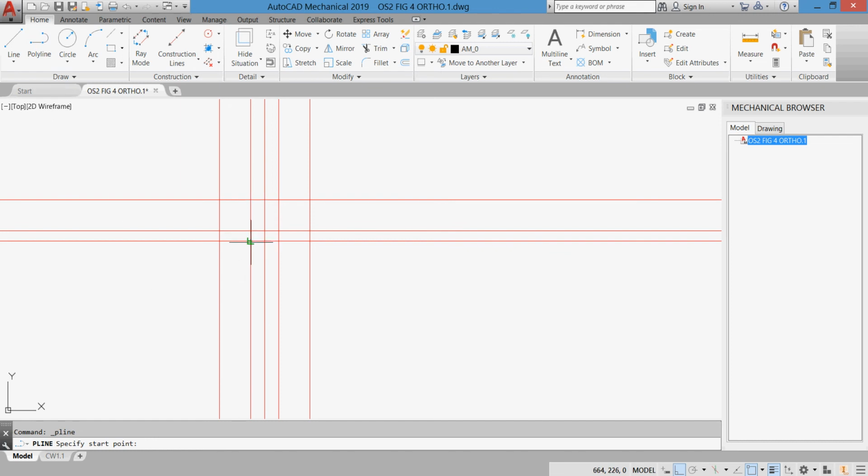My tunnel starts from here to here as a line, and then it goes as an arc. So I go down, click arc, or type A on your keyboard. Now I need a line, so I click line, or type L. This is my tunnel. We said that we'll offset it by 8, so 8, enter, and this is my 8.